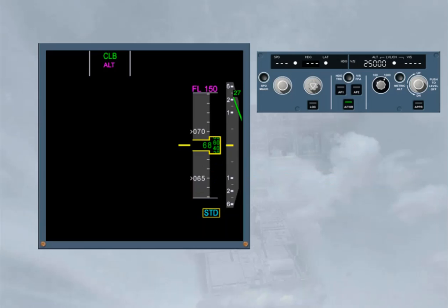The vertical speed indication is displayed as shown. Note, the current vertical speed is 2,700 feet per minute in climb. If the climb must be stopped, the vertical speed knob must be pushed. The target is shown on the FMA and can be FPA or VS according to the selection done by the heading vertical speed track FPA push button. When the vertical speed reaches 0, orders are given to maintain it. Note, the constraints are disregarded.